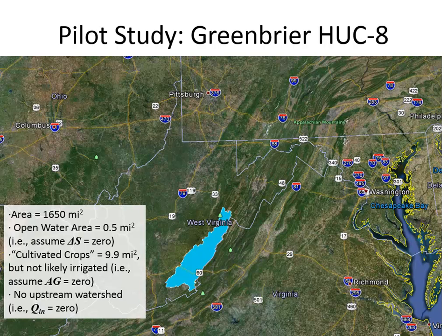And there are characterizations of large volume water users, like if there were any mines in the area that are using water, or towns that have water treatment plants. But there is a very limited number of large volume users. So basically this is a wild watershed that just doesn't have very much human impact on it yet. The advantage of starting with a watershed like that is that it eliminated variability and would allow me to try and predict the runoff as a function of the evaporation and the rainfall.